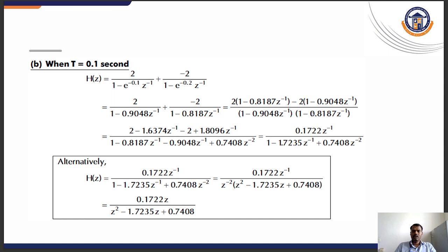So the conclusion is that when we use the impulse invariant technique, the aliasing problem will occur. In order to avoid the aliasing problem, we go for the bilinear transformation, but it has problems like pre-warping, which has to be avoided. How we avoid it is by using s = (2/T) (1 - z^(-1)) / (1 + z^(-1)). With the help of this, we avoid the warping problem.